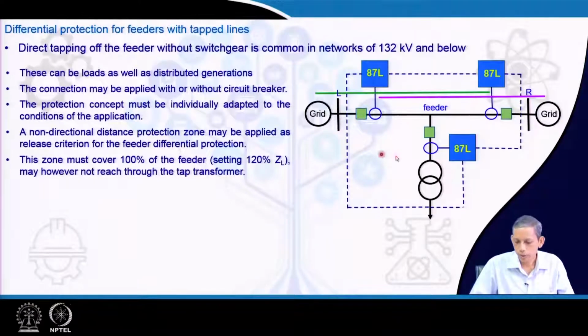Now, if you have communication information from all these, fine, you can use the corresponding KCL, and each relay can decide very efficiently. But sometimes the communication link may not be available, or there is no provision for a communication link, so how to handle that? And at times there may also be a failure of communication, so how will the corresponding relay handle that situation?